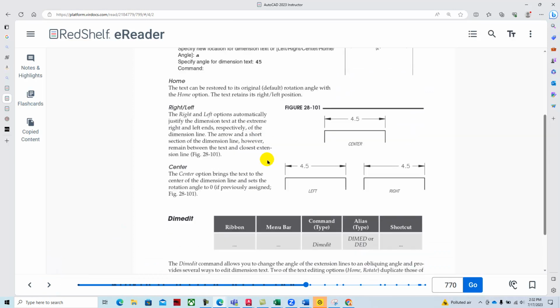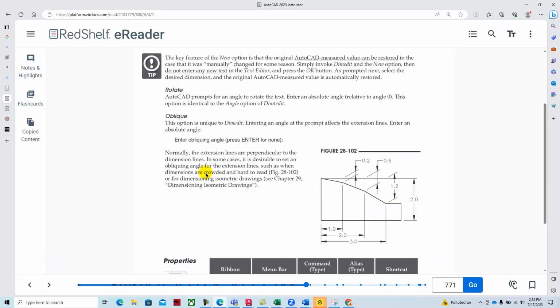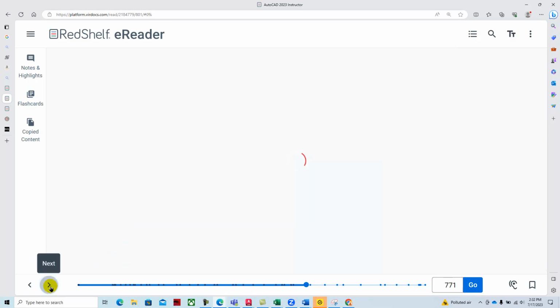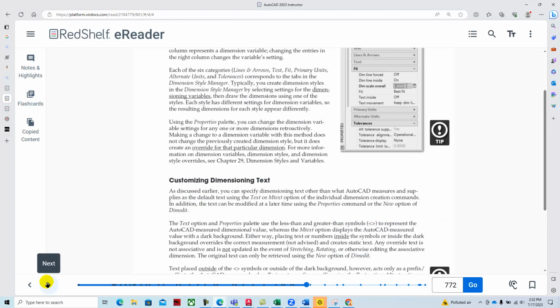All right, and so, just more information about editing dimensions, moving them. Grips are the easiest way to move them. And so as you work with your dimensions, you can move them around. You can pull up the properties menu like I did on the center mark and make adjustments, like turning off the center mark or changing the dimensional precision.